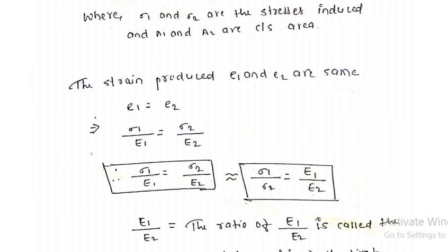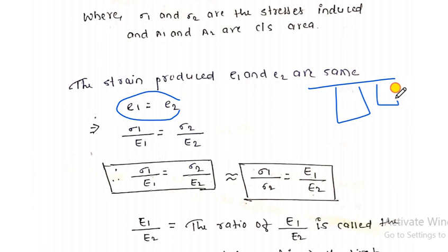So according to the second property, the stress induced in the composite sections by the different materials, either aluminium or copper, whether it is compression or extension, whether tensile or compressive, the stress induced in the composite sections is the same, because it is fixed at one end rigidly. So the extension taking place in the composite sections is the same; both the bars have the same extension.